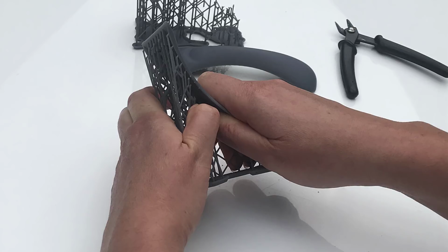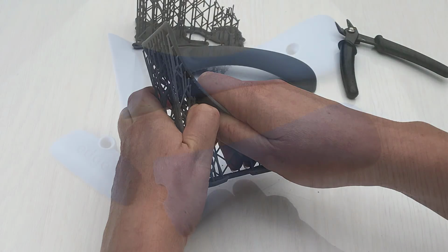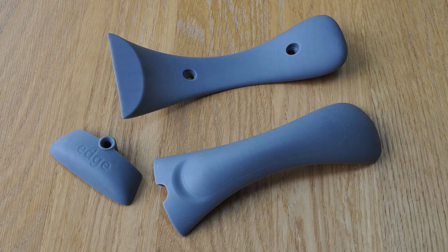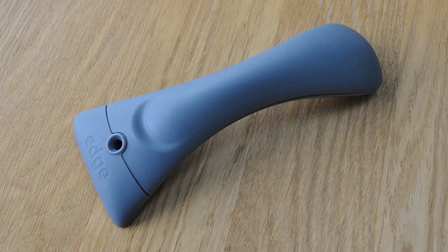As mentioned earlier on in this video, we made sure that the supports were on the B surface or inside of the parts, and, should you wish, the witness of the tips can be sanded away from the final part. Here's the final parts from the printer, and you can see that we have retained a great amount of detail. The edge logo and the handle recess have printed evenly and retained their crisp edges. These parts can now be primed and painted for a full aesthetic prototype if necessary.